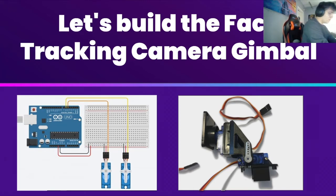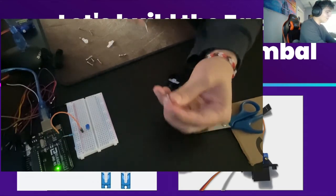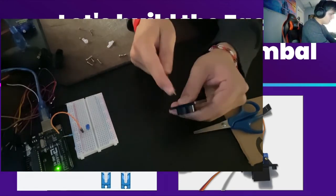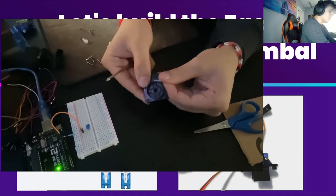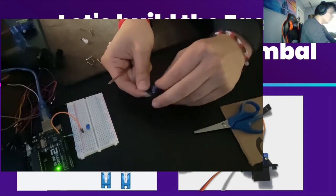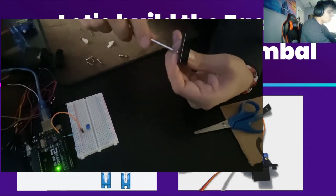Okay, so from there, we're going to put this inside the gimbal. We're going to put it horizontally, sorry, with this facing that way. Then we're going to get these screws that also come in the packet for the white parts of those servos. Use the screw that came in the box if you have it, or if not, you can use any screw. Then we're going to go under it and start screwing that in. The holes might be a little bit small, but the screw will be able to go in. Once you get it inside that hole, try to put that white part into place, and then you can just start screwing from here, and it'll go through that white part.